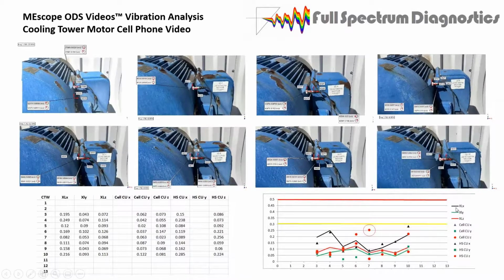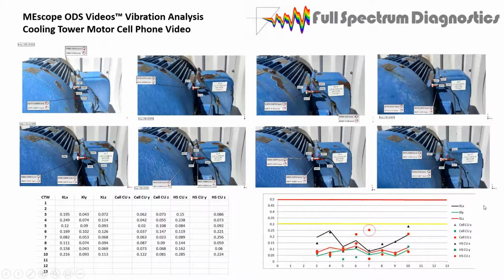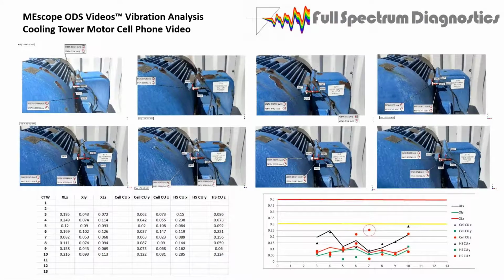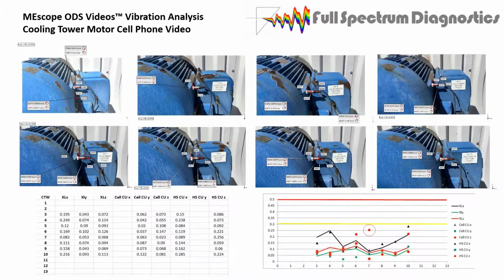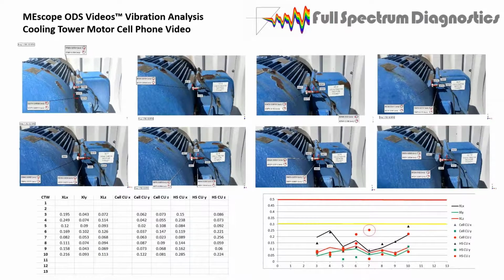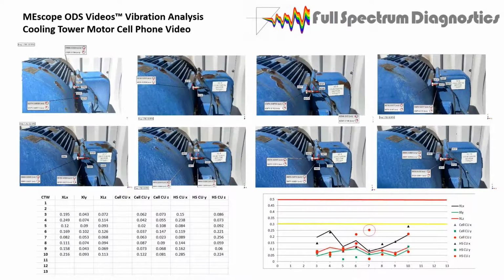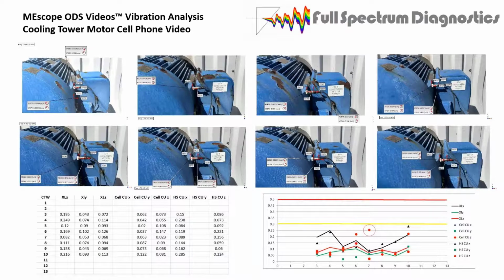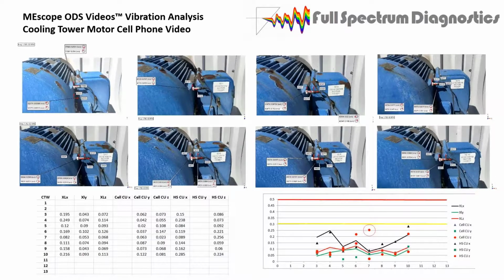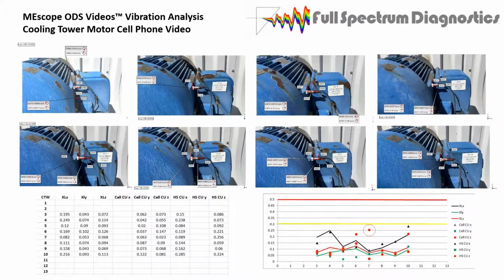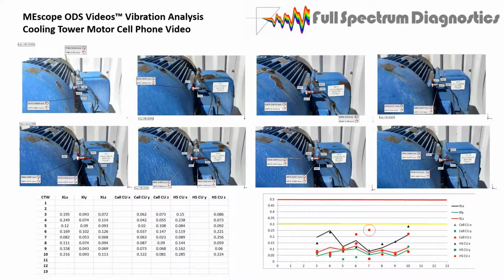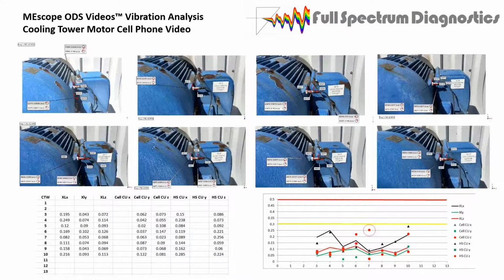And you can't see it, you might be able to feel it, the vibrations that are causing a looseness or a misalignment or a broken weld or what have you, foundation problem. But this is the way to provide amplification to see it, rescaling the amplitudes and pulling out the meaningful data from the video analysis.